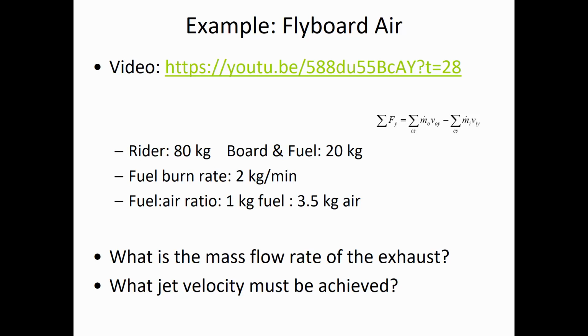So there has to be 981 newtons of force to keep this 100 kilogram rider plus equipment level. And you'd need even more force than that if you actually want to go up. If you want to be able to accelerate upwards, then you'd need more force than the 981. But let's just say how much is required to maintain level flight.